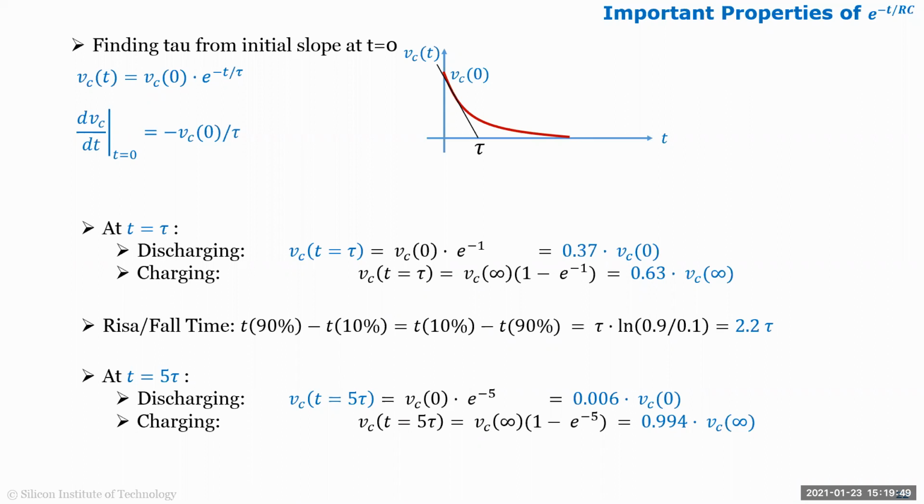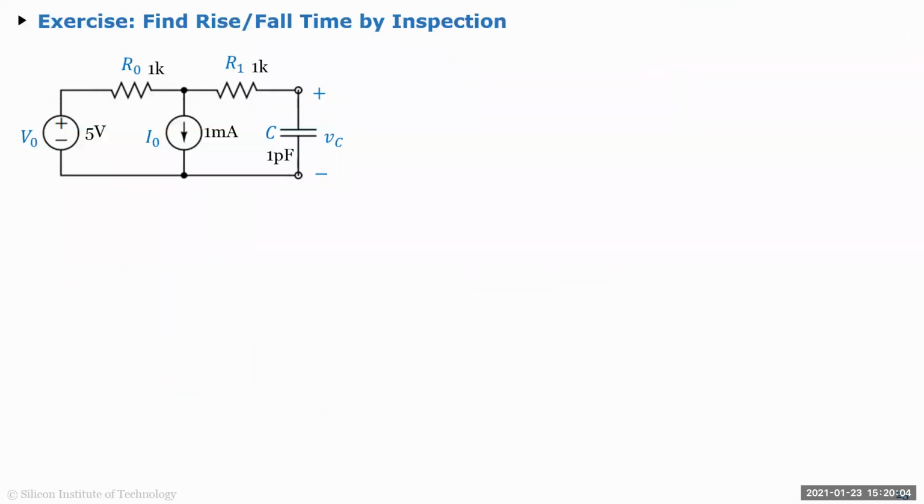But if you are doing a 16-bit ADC or an 18-bit, you want to settle even closer. You want to get to 0.01%. Otherwise, you're not going to settle to the value you're trying to reach. So these numbers are good for most cases, not all cases.